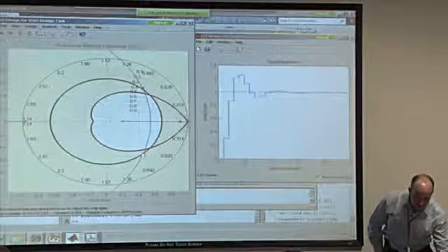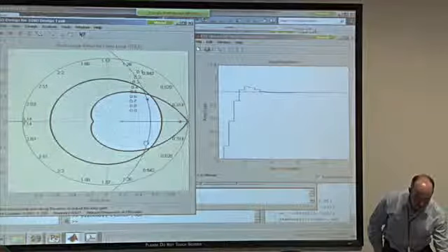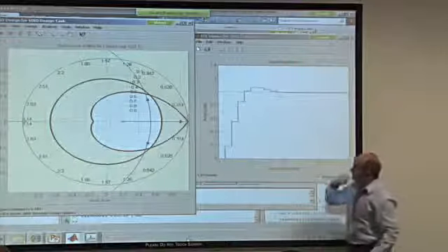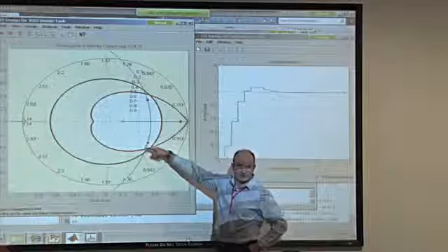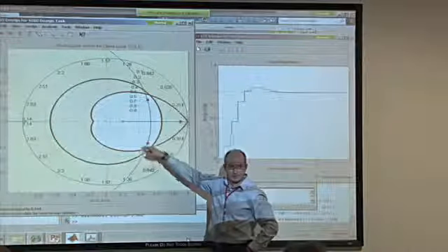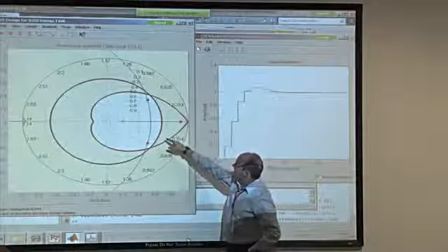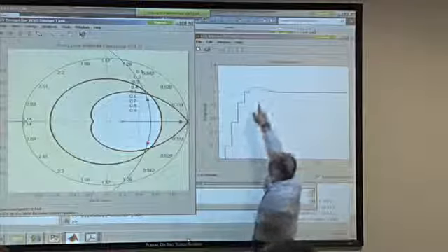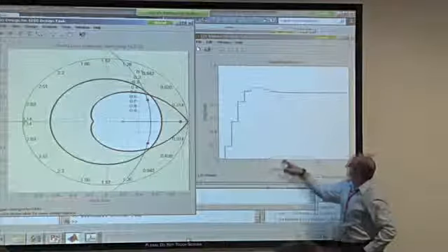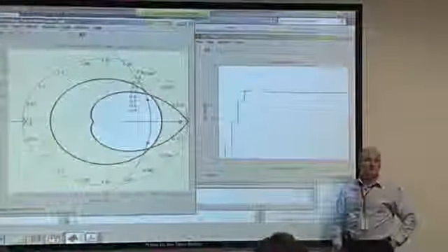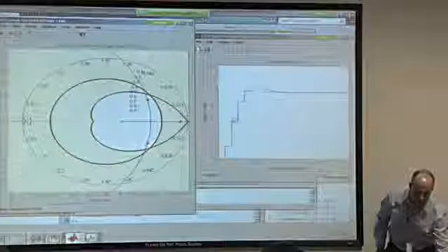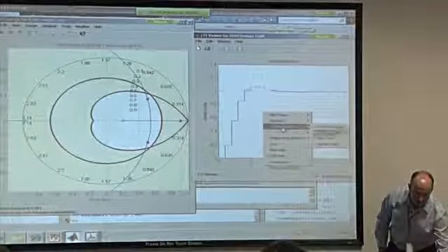And now we'll select, again, maybe just move it to about there, for example, because we've got a little bit of robustness margin in here. We don't want it right on the border. We'll pull it in a little bit. Well, we can see now we're meeting the 16% overshoot rule. I'd believe that. And the settling time to within 10 seconds, we're good too. Okay, we can measure these things if we want to on this response.